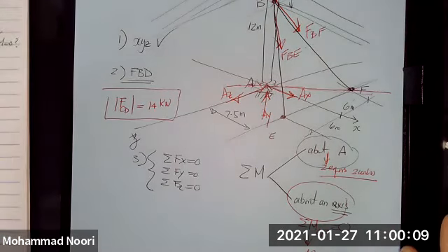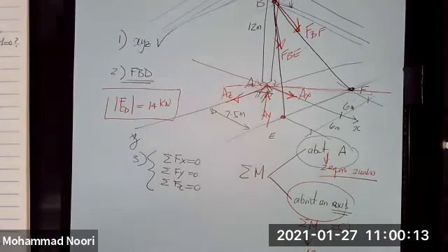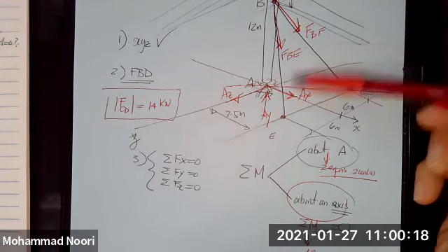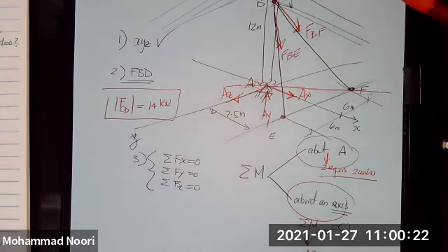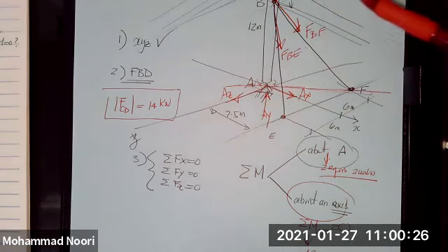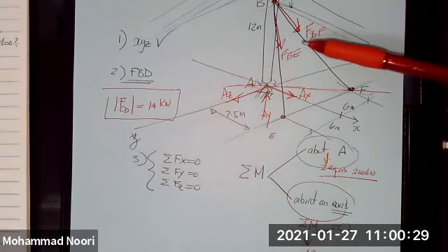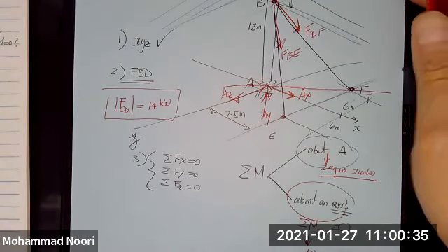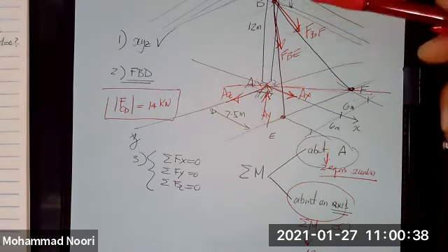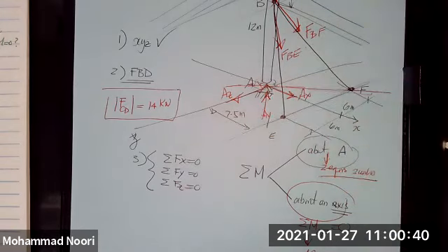So now, how do I proceed with solving it? Well, obviously, the first step is you set up the vector equation for all the unknown or known forces you have. In 2D, you are only dealing with magnitudes, because the moments are just that magnitude times the perpendicular distance. In 3D, equilibrium is a vector equation.